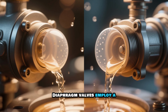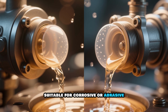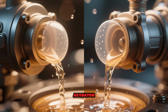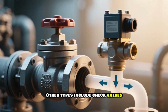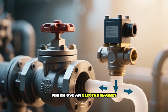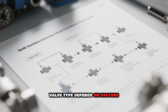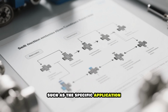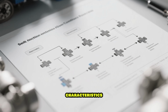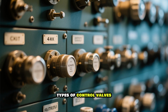Diaphragm valves employ a flexible diaphragm to control flow and are suitable for corrosive or abrasive fluids, as the diaphragm isolates the wetted parts from the actuator. Other types include check valves, which allow flow in only one direction, and solenoid valves, which use an electromagnet to control flow. The choice of control valve type depends on factors such as the specific application, fluid being handled, operating conditions, and desired performance characteristics. Okay, so these are some of the most common types of control valves.